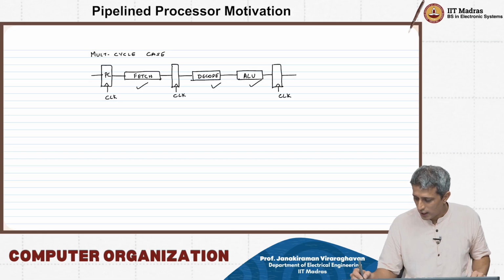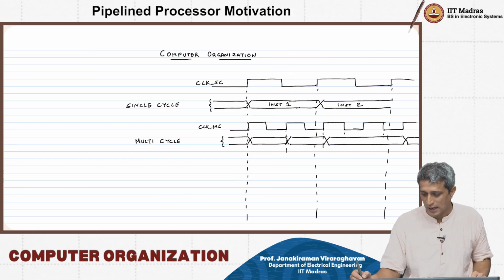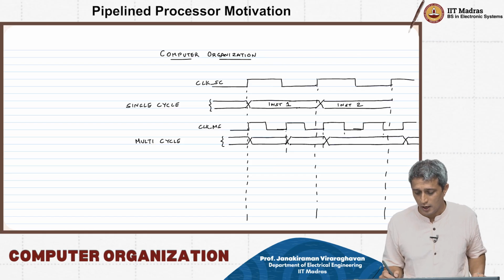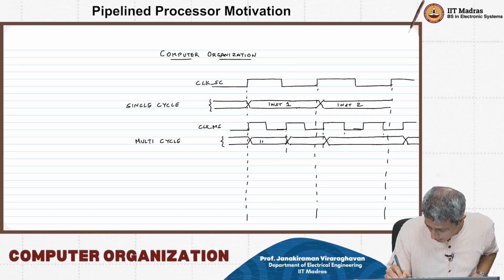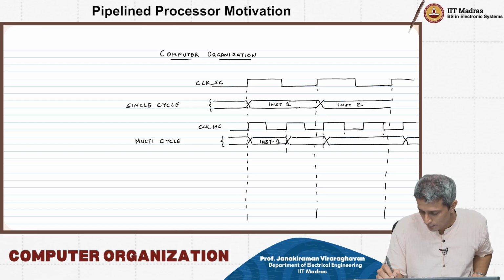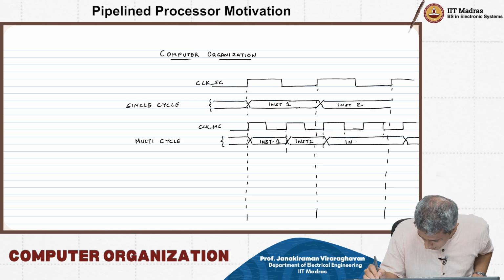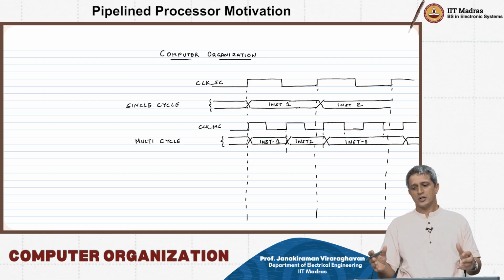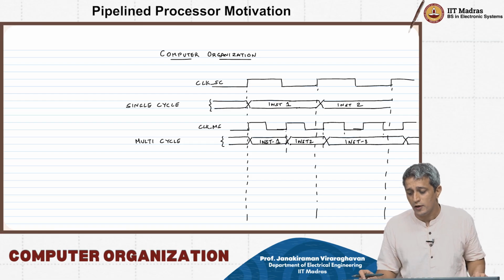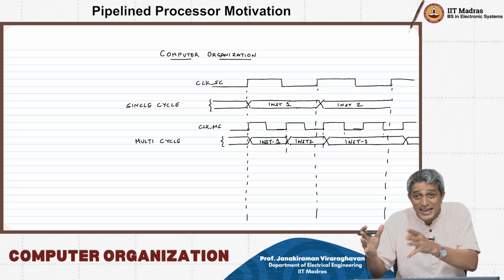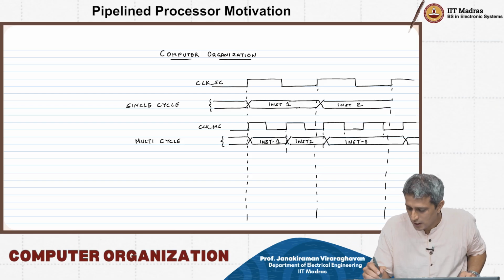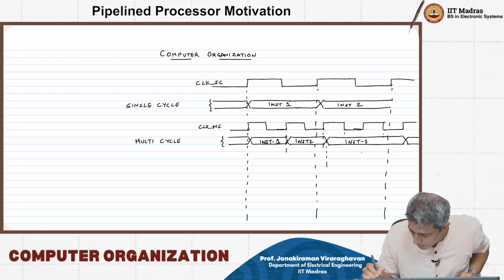Okay, that's why if you look at this particular timing diagram that we drew here, okay, we are saying that instruction 1 was executed in this clock cycle. This is instruction 2. This is instruction 3. Okay, it is taking some 2 clock cycles something, but effectively if you look at what is happening in instruction 3, it is effectively going to happen in this particular way.